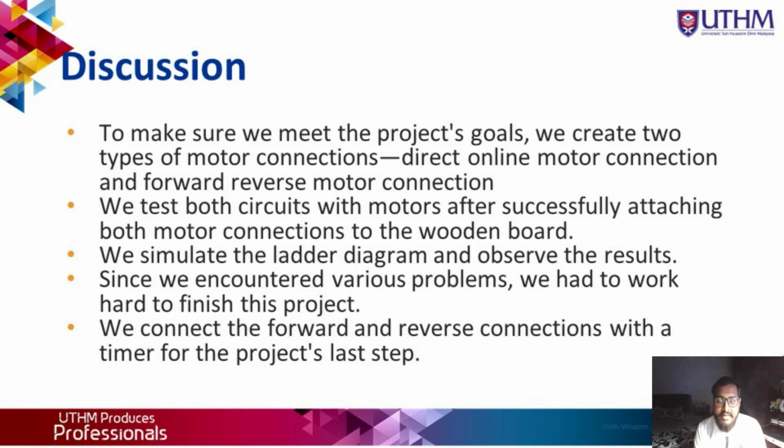After that, for testing with motors, safety is essential. Handling the motor shouldn't be done with bare hands. When handling the motor, always use protective gear like gloves and make sure to stand on a rubber mat. Additionally, we check to see that the PLC module is free of unwanted components like conductive waste. Next, we test both circuits with the motor after we successfully attach both motor connections to the wooden board.